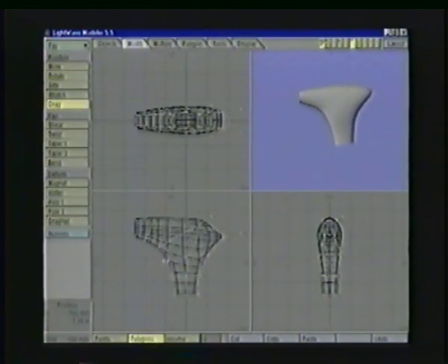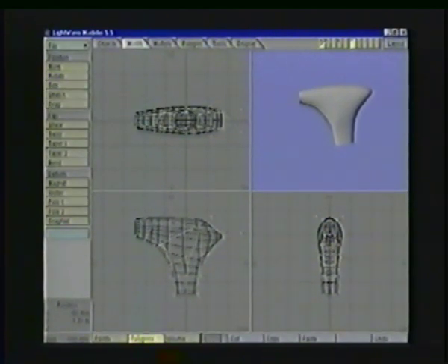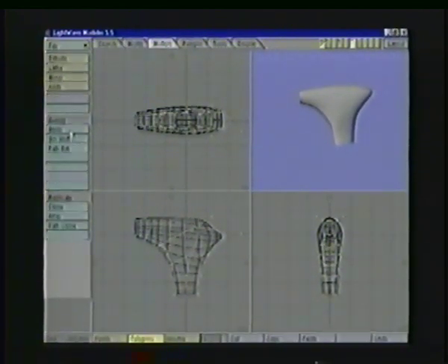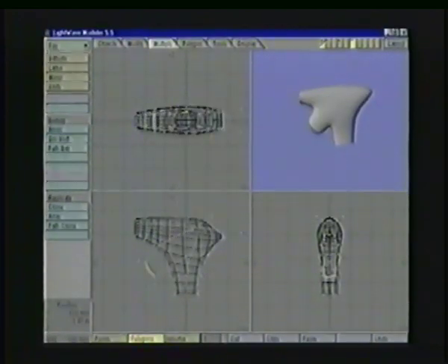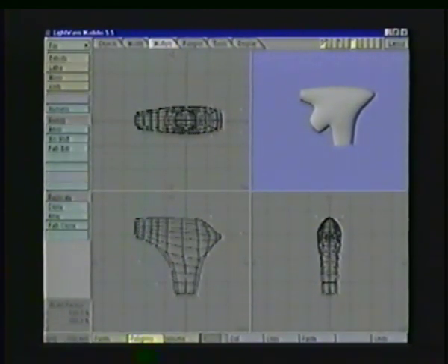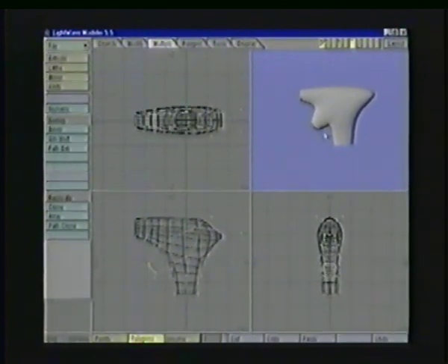and I'm going to use the drag tool to open up a little bigger space right here where I want the trigger to come out and have a trigger guard. In polygon mode, I'm going to simply select the very end polygon. I'm going to use the bevel tool under multiply, and I'm going to bevel without an inset and with a shift of, I'm just guessing, about 100 millimeters. That might be too big at first. It doesn't look too bad. And I might want to reposition it a little bit. Hit H, maybe stretch these in toward each other a little bit and round it off.